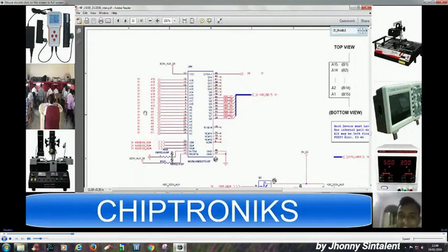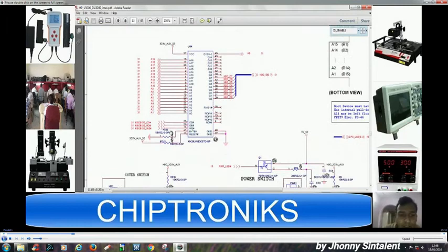Now the EC inside the IO controller will interact with the EC BIOS present in the BIOS chip. So how can we check this interaction? We can check this interaction via an oscilloscope. Now we have already checked this, so we'll go to page number 31.